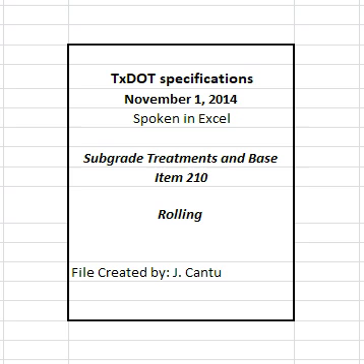Operate rollers at speeds that will produce at least 10 blows per foot unless otherwise shown on the plans or approved. Pneumatic rear wheels are allowed for embankment, subgrade, and base. Equip each vibrating drum with separate frequency and amplitude controls, controls to manually start and stop vibration, and a mechanism to continuously clean the face of the drum.